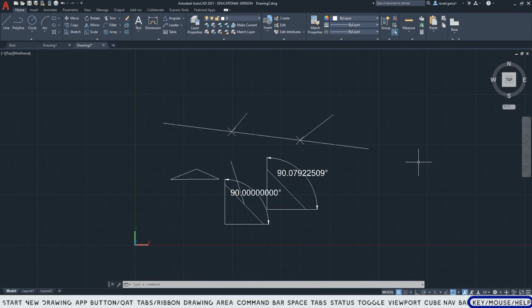Now I have no idea where the divide command is or where the draw display point type command is, where they live in the ribbon, but I do know the keyboard commands. Now of course you're not going to just magically know all these commands, but if you want to find them, you can use AutoCAD help. Now most people just disregard the help function, but AutoCAD's help function is actually quite useful. Like most libraries, you can press F1 to open it.